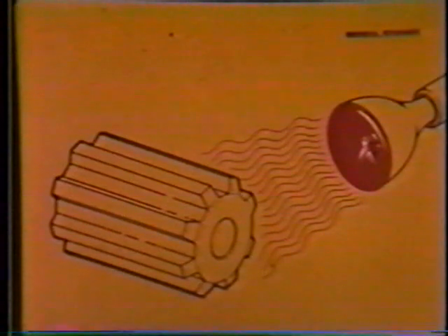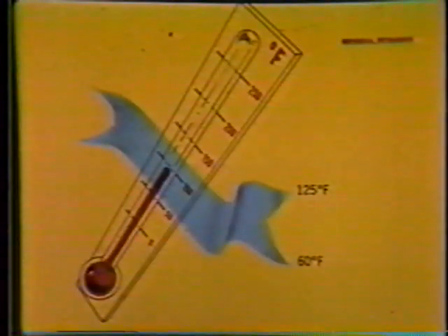Heating may assist in opening discontinuities and shortening dwell times, but the practice generally is not recommended. Best sensitivity and reliability is obtained with penetrant and specimen temperatures between 60 and 125 degrees Fahrenheit. And in most instances, a dwell of 5 to 30 minutes is sufficient. Longer dwells requiring the rewetting of test surfaces. Rewetting also makes removal of dry penetrant easier.